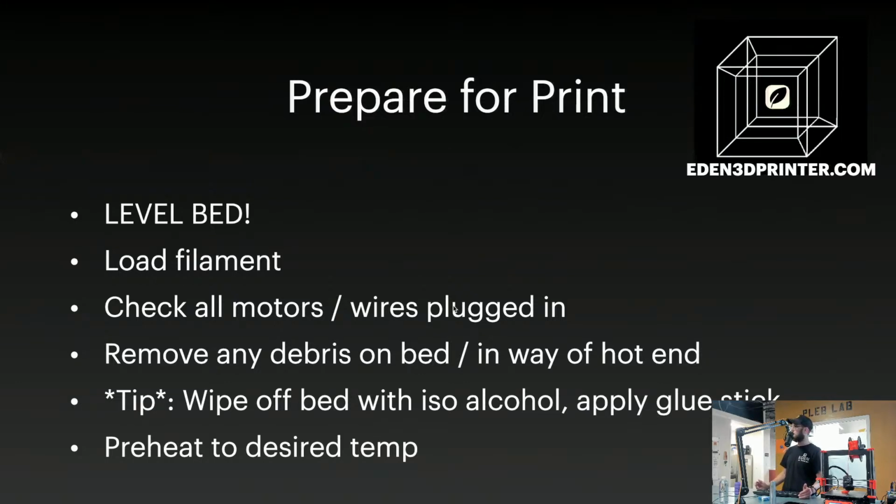There are other tips and tricks as well. Always have some isopropyl alcohol with you. I don't have towels, but I did wipe that off with a towel. It gets your finger grease off of the bed. Even just touching it 1 or 2 times, even if you just washed your hands, you can add a slight amount of grease and put a slick layer where the filament might not adhere properly. Another good tip is the very strong sticky hairspray. That works very well if you have the strong version.